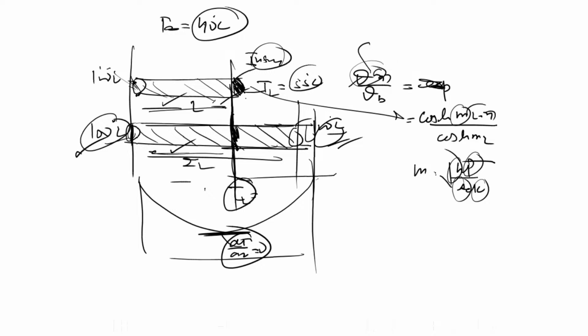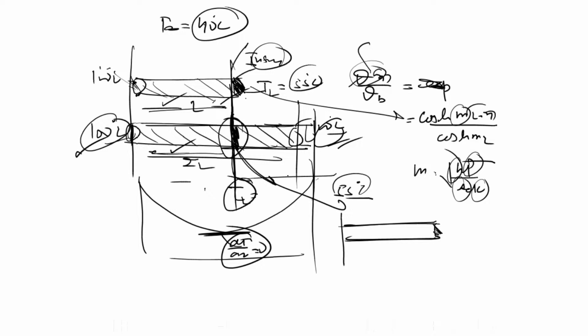And since the center of the surface will act as insulation, this can also be treated as half of the length, and here insulation is there. Yes or no? And m is the same. Then whatever temperature at this point, the same temperature at this point. The temperature will also be 55 degrees Celsius at this point. Yes or no? Because length and diameter is same. Then the right hand side is same, so the left hand side will also be same.